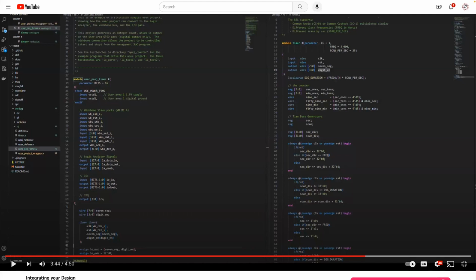There's a similar set. So basically there's 3 wires for every pad, 0 through 37 in the chip. And you need to make sure that if you are connected to the input or the output, that you tie the IO_OEB signal appropriately. It's a bar, it's inverted. So it's an output enable inverted. So high is an input and low is an output. Tied low is an output. So make sure you get that connected correctly. Otherwise, your signals will not propagate through to the pad. So that's one key piece.